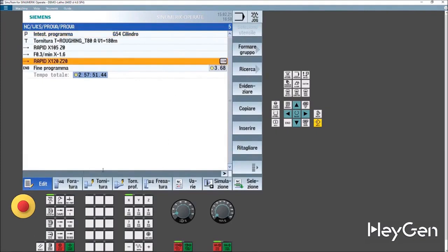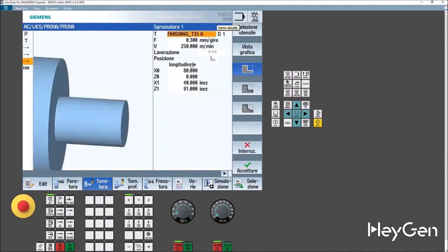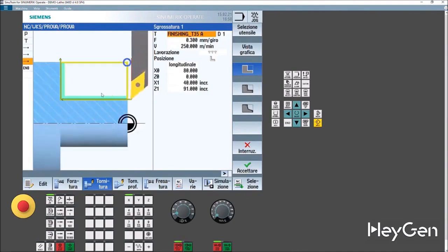At this point, there are fixed cycles that allow you to rough the piece. So with this, you can already do cylindrical turning. You need to make a pin. Cylindrical turning and facing. Turning, roughing. Here you already have fixed cycles, so the ability to simply rough the piece, removing material from the section, let's say. Perfect.